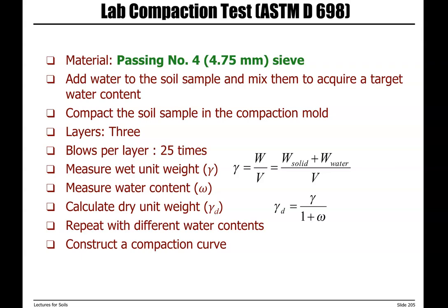First, we need to prepare our soil. The soil that we are using is passing from number 4. So the material we need for this test is finer than number 4. You have your soil sample. Start by adding water.